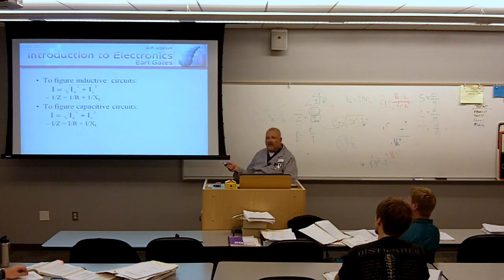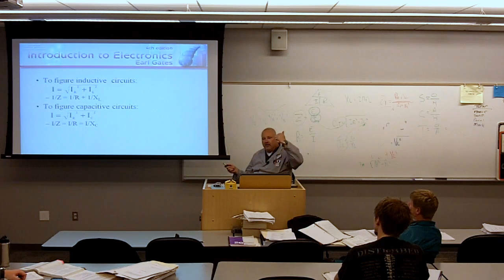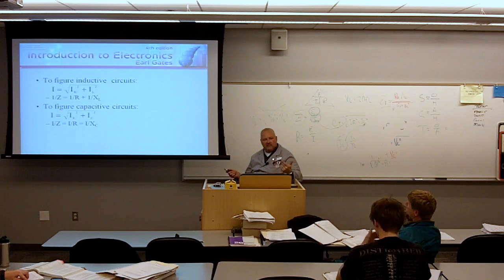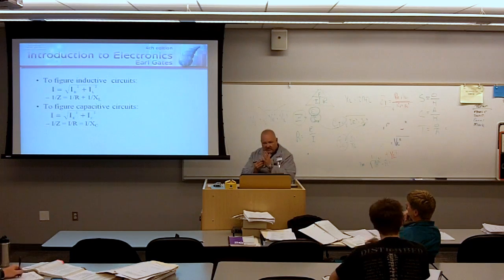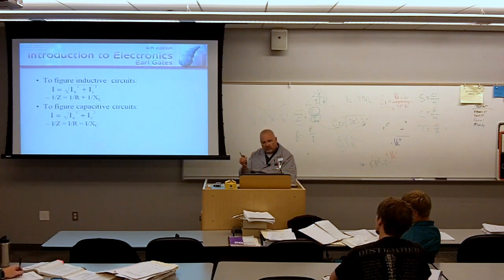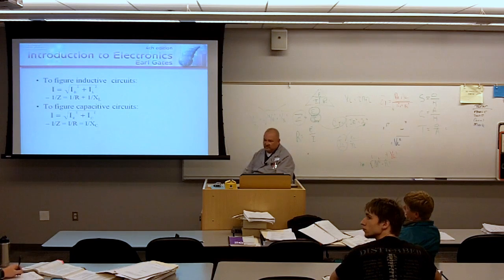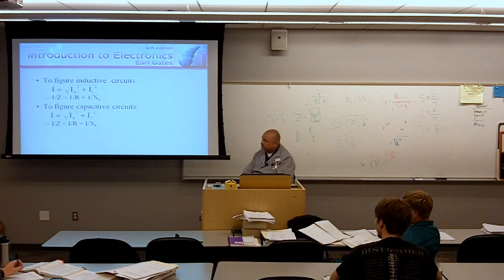In AC, come on, help me out, guys. First thing is we talk about what kind of voltage source. In AC, is it series or parallel? Parallel circuit that contains a resistor and an inductor. How do I know that? I'm taking the vectoral sum of the current through the inductor and the current through the resistor. Does that make sense?